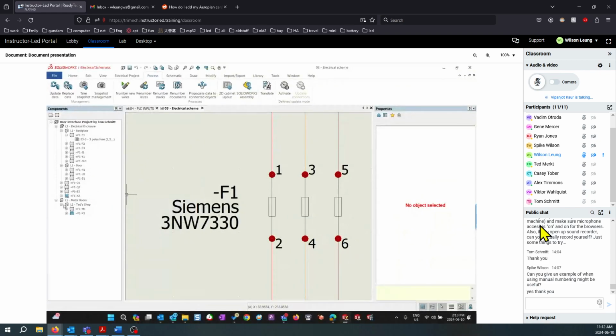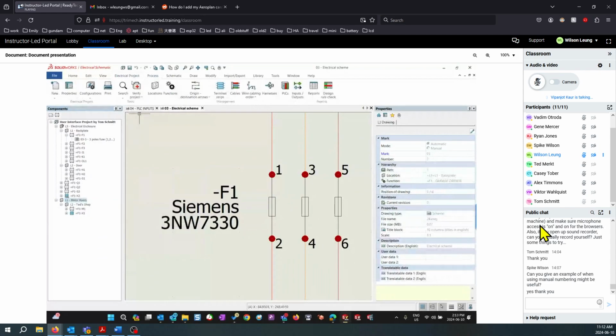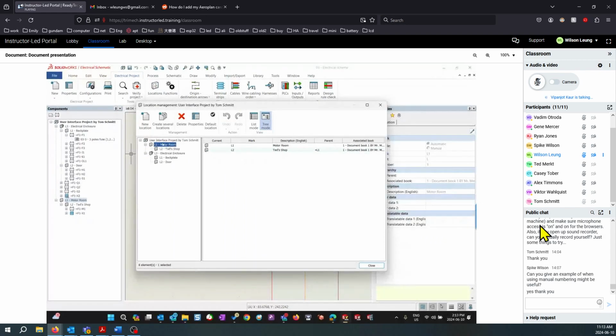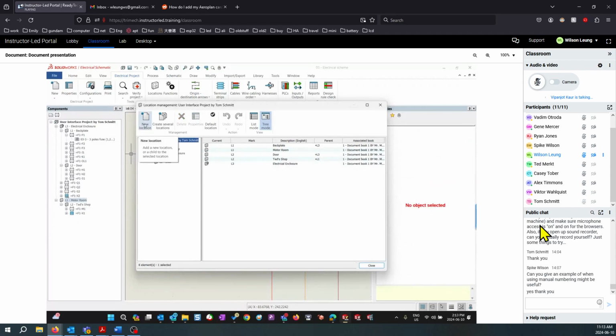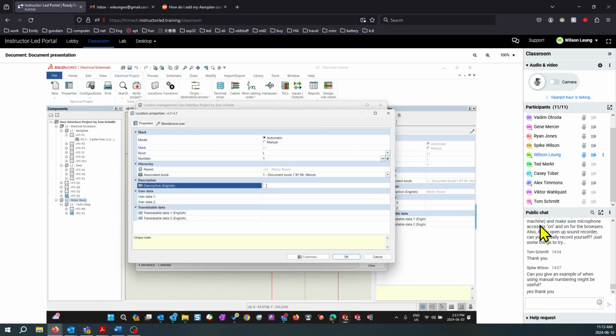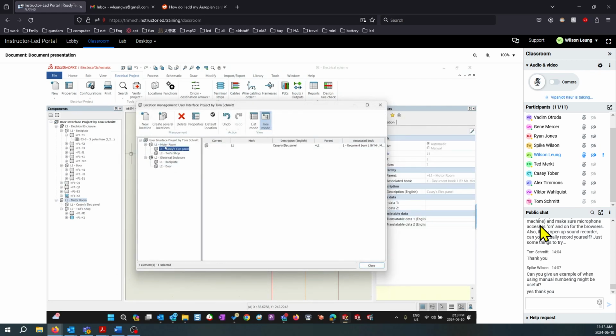And then I can create a brand new location that would be a child location, or project tab, locations, we will do that in lesson 15. I can pick an existing location, the motor room location that has Ted's shop. Once I pick the name of the project and click new, it gives me a main parent location. If I pick an existing location and click new, it's going to give me a child location. So I'll call it Casey's electrical panel, something like that. Right. So I created a second child location. How? Picking an existing location, then clicking new gives you the child location.